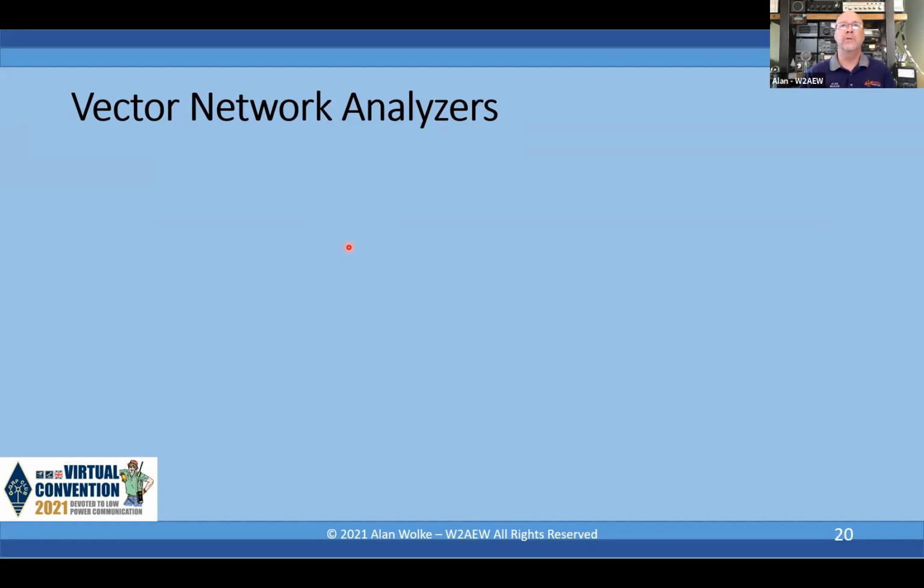For the Tiny SA, what range of attenuators would we recommend? Unfortunately, John, I don't have direct experience with the Tiny SA. I don't have one, so I don't know what signal levels it is rated for. I would say probably 10, 20, 30 dB are good ones to start with. Probably nothing less than 10, just to put you in the right range. But again, I don't know what the reference level settings are and what the absolute max rating of the Tiny SA is. So maybe some others can chime in on the chat with that.